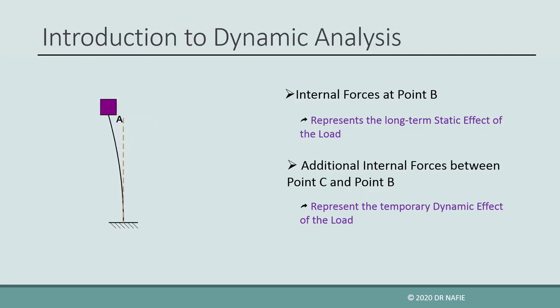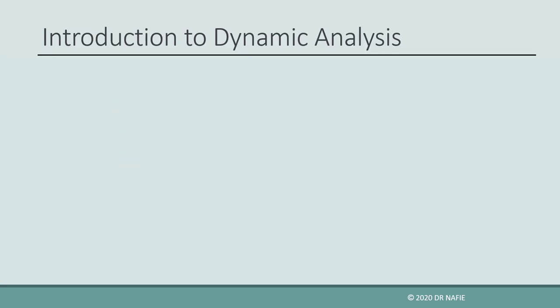If the force is suddenly removed, then the cantilever will vibrate in a free vibration around point A until the motion is damped out and the cantilever is stopped at the undeflected position at point A.